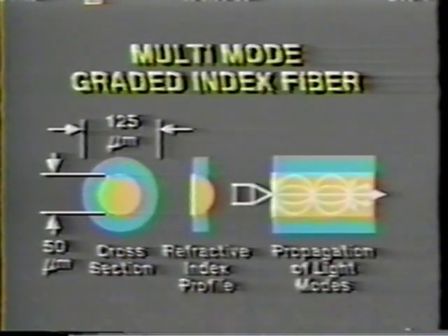The core region, that portion of the fiber which actually conducts light, has a graduated refractive index profile. Since light may enter the core from a variety of angles, this graded index profile permits the fiber to function like a lens. Light traveling down different paths or modes is gently guided to repeated points of convergence as it tries to spread out. The graded index, therefore, reduces dispersion, allowing multimode fiber to provide a good information-carrying capacity over moderate distances.